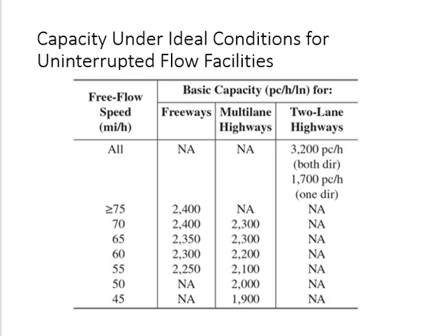Just the last sentence. They have two lanes, and each lane is for a different direction. In those cases, one lane has an effect on the other lane as well. So the lane which has a higher volume affects the other lane, even if it has lower volume. So low speed in this lane will also decrease somewhat the speed in the other lane as well.